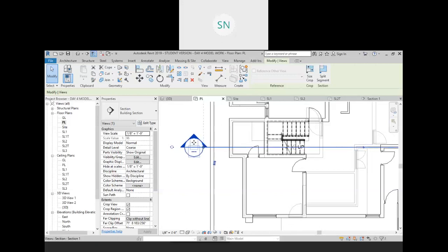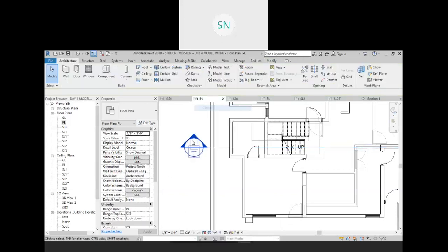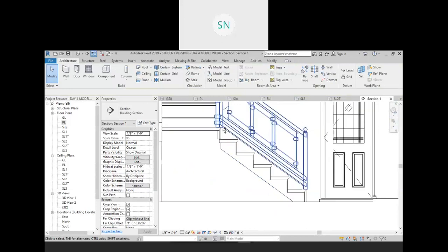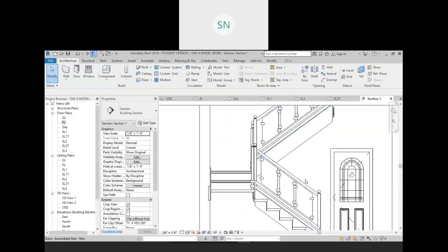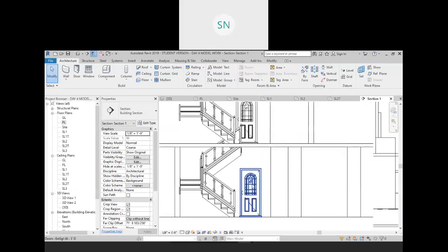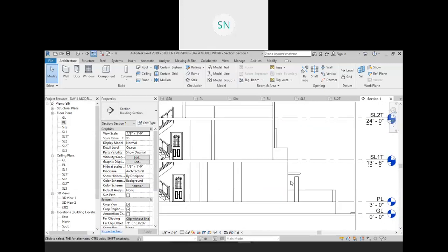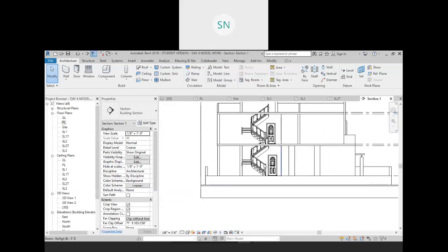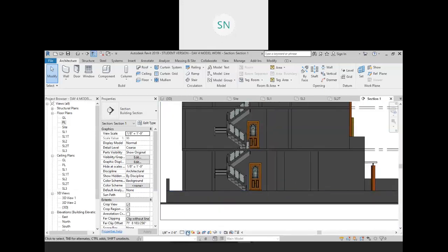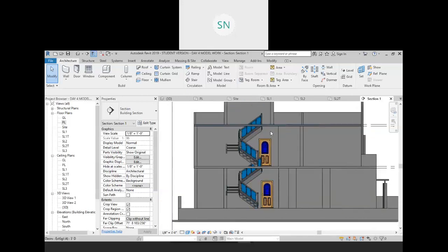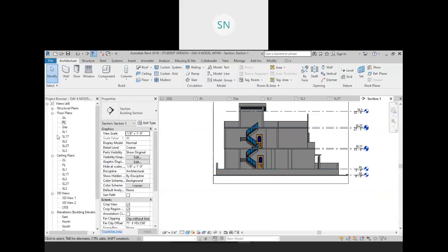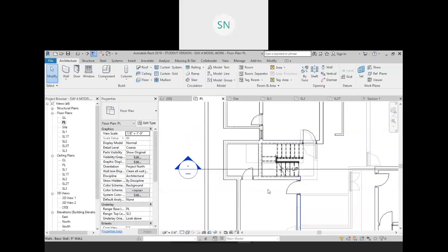See it? Just double click on this view, and here we have, right? So this is the full and this is the trimmed portion, the section drawing, right? That door is there. These are the columns which are visible. Change your visual style to realistic or shaded, whatever options you find comfortable, right? So that easy to create your sections, not like AutoCAD.